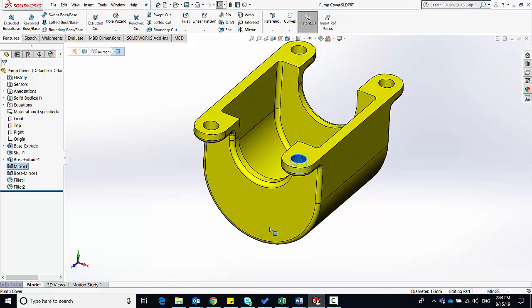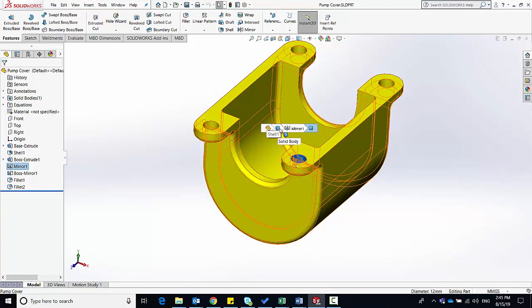In this case, if I press the circular face related to the hole, move my mouse away, and press the D key, I can bring the breadcrumbs closer to my mouse. This way I can select either the face itself, the feature that helped create that face, or the solid body, which then relates to the part as well, making for easy selection.